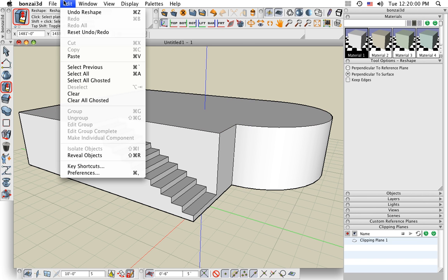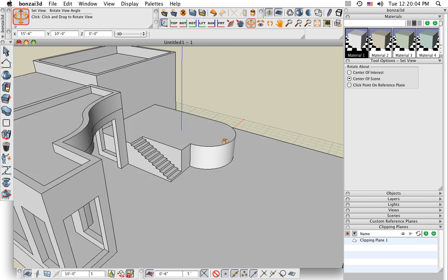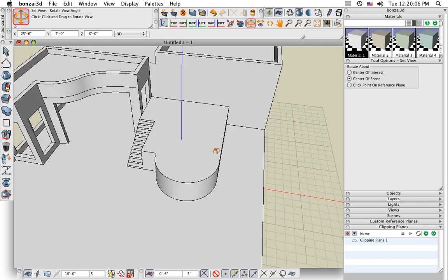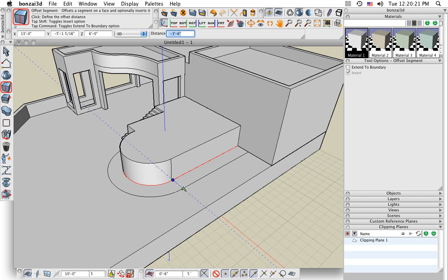Okay, let's bring the other objects back. See how this looks in context. Great. How about a set of stairs here that curls around the curve of the platform and moves up to this structure here? Let me start by offsetting again. So I can use these two edges here, offset those out parallel,